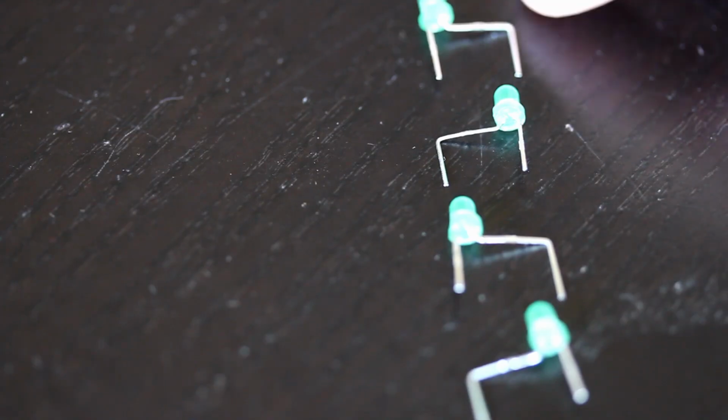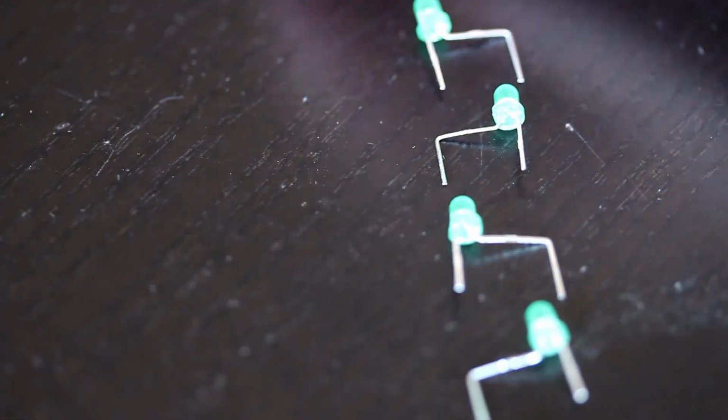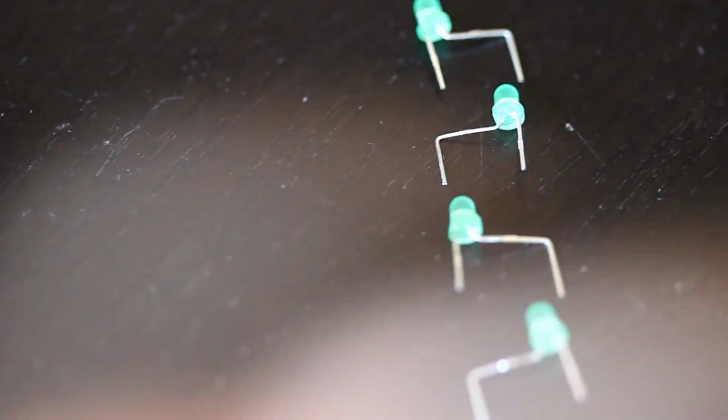Since the LEDs have such a large LED portion of it and the tie strips are pretty close together, these LEDs will get in the way of each other, so I went ahead and bent the leads in a way that the main LED can be staggered. These are all in the same direction, where the anodes are all on one side and the cathodes are on the other side. So let's go ahead and plug the resistors and LEDs into the circuit.